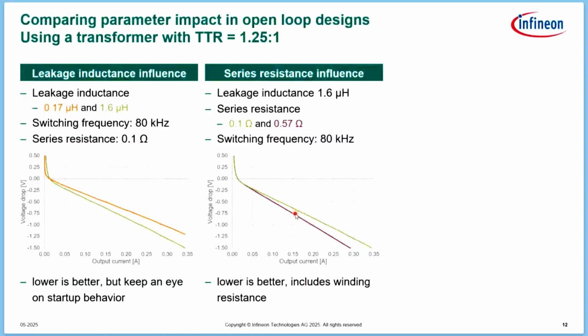However, just keep in mind, the application usually, when it's running, is somehow drawing a constant current out of the supply, because PWM switching is in most applications not switching so fast or not really switching between a lower level and a high level. There are some exceptions, yes, but most applications stay at constant switching frequencies, and therefore you could optimize your circuitry for the expected voltage drop and just increase the input voltage to the complete circuit, and therefore you would still have a stable output voltage on your system.